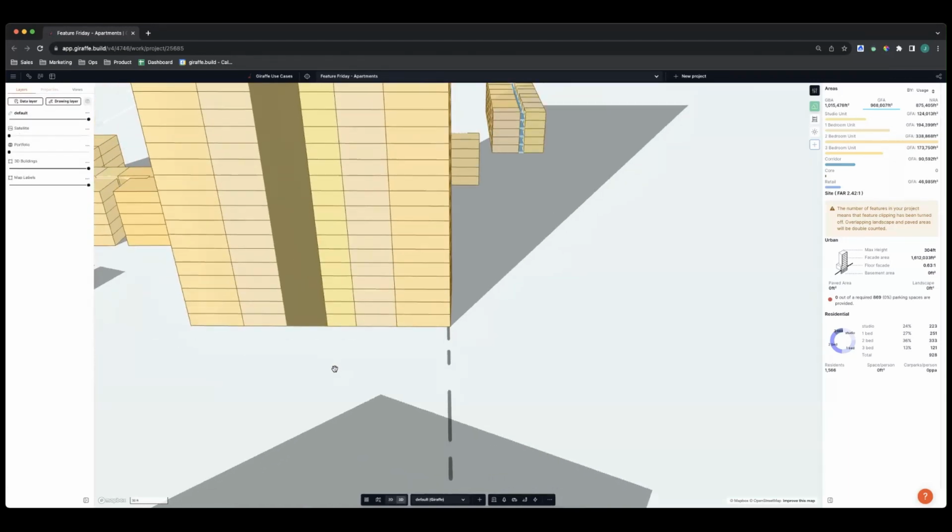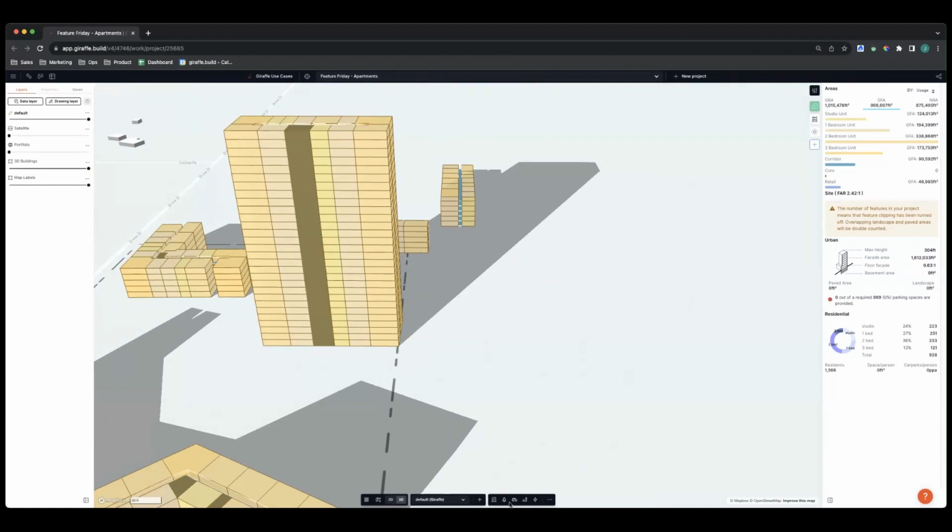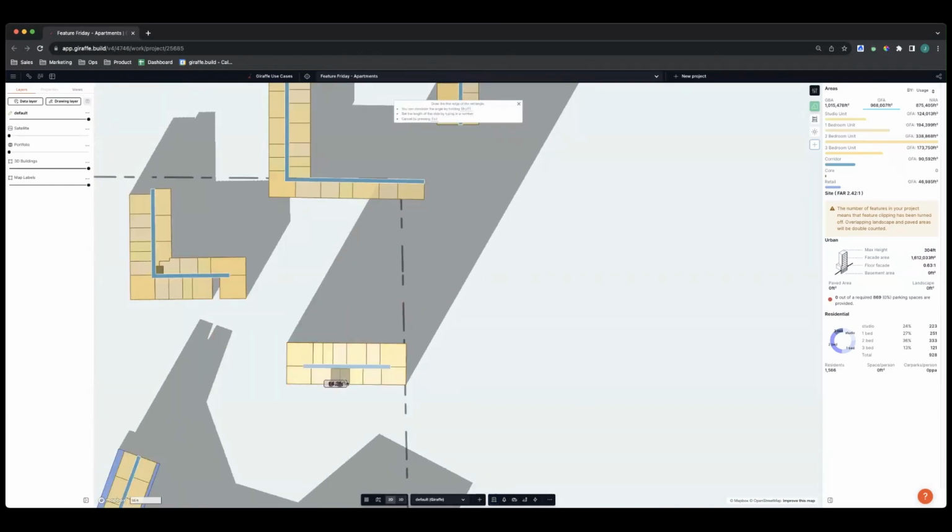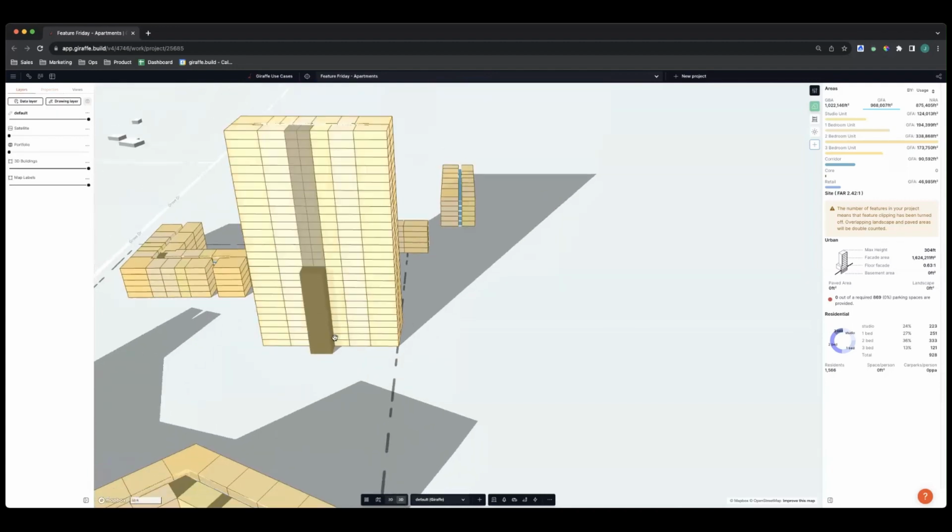And that tells the algorithm to turn those 2 spaces into core. And if it's not big enough for the size, then I can just draw externally, if you want to do external core, an additional core space to give us exactly what we need from a structure point of view. So I get that one a fair bit too.